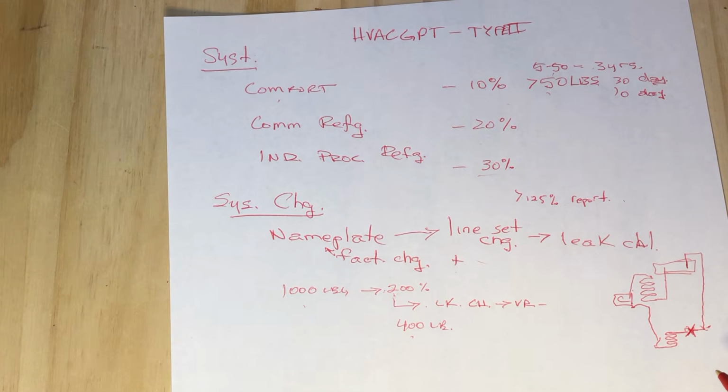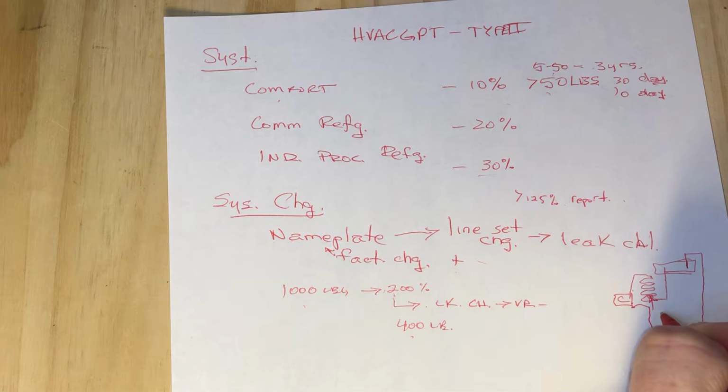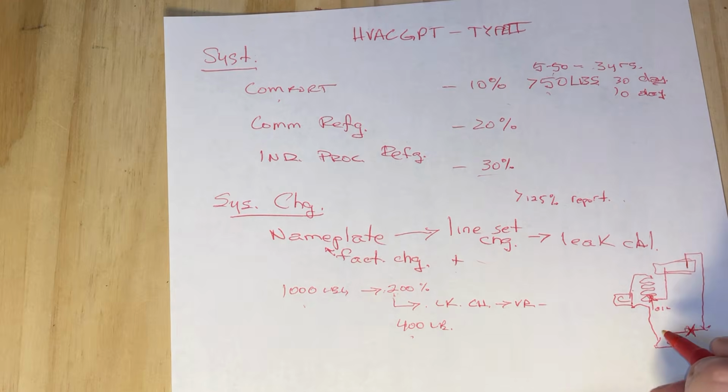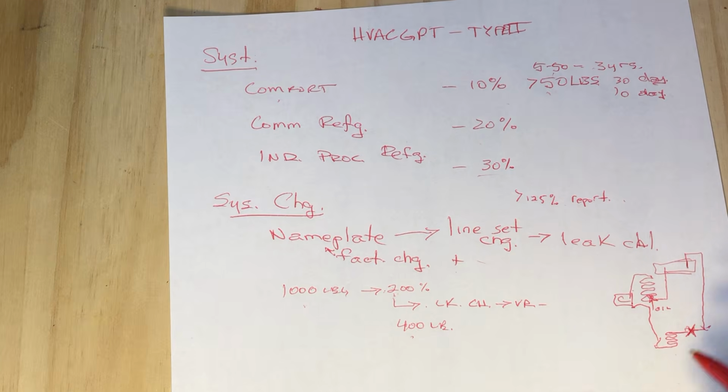And generally, when we're doing this type of work with a system, we want to make sure that the system doesn't have any leaks with traces of oil. We can do a visual inspection. Let's say we see a dark spot of oil on the condenser coil there, then we could have a leak, and we would probably find and repair that leak, and then do the verification that there are no further leaks. And that verification could be a standing pressure test, where you're just taking your tank of nitrogen, which you already had if you did the leak repair, flowing through the system anyway.